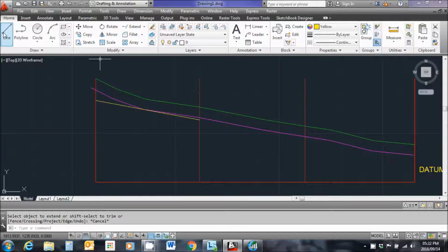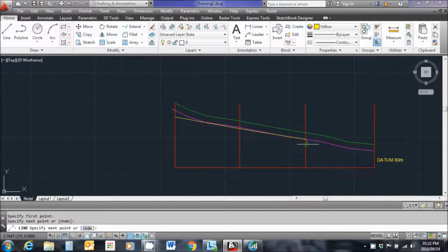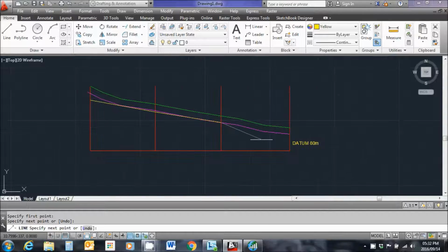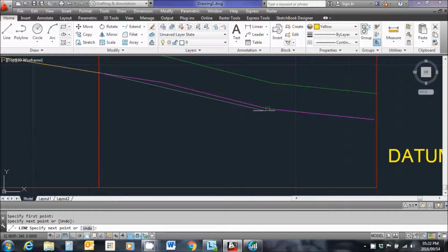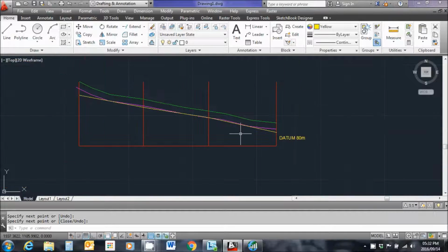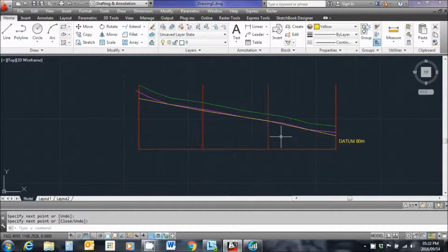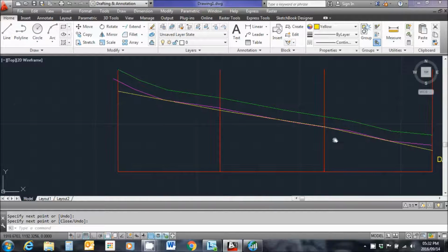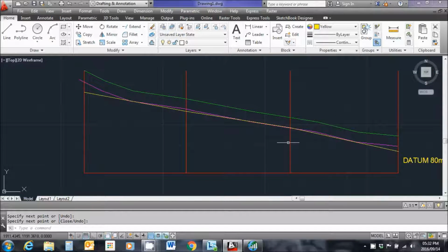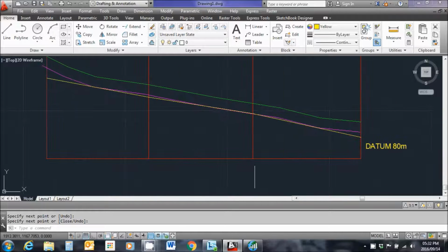So I'm going to do another line now from this point to that point, and now again I have the same story where I have sort of double kinks, and I'm just going to make this one touch approximately over there. Good. And that's good enough for what we're required to do as part of our drawing function. The sewer design function is something that we learn about at a later stage. So what I now have is a provisional sewer alignment going from manhole B1 to manhole A6.